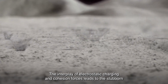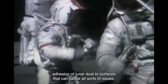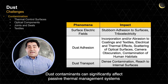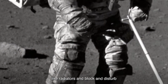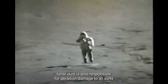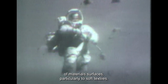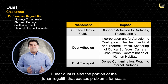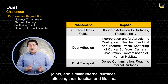The interplay of electrostatic charging and cohesion forces leads to the stubborn adhesion of lunar dust to surfaces that can cause all sorts of issues, as listed in the table on the right. Dust contaminants can significantly affect passive thermal management systems, like radiators, and block and disturb measurements from optical systems. Being glassy and abrasive, lunar dust is also responsible for abrasion damage to all sorts of materials surfaces, particularly to soft textiles. Lunar dust is also the portion of the lunar regolith that causes problems for seals, joints, and similar internal surfaces, affecting their function and lifetime.